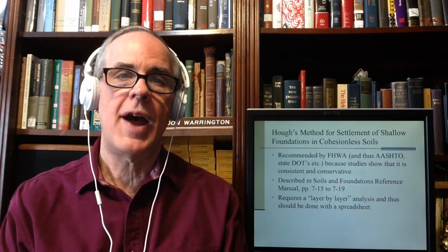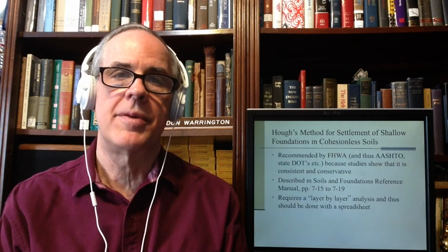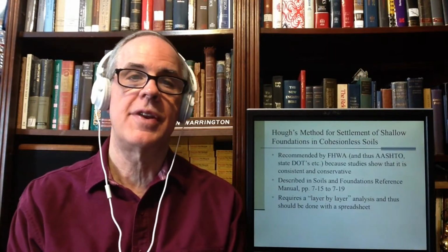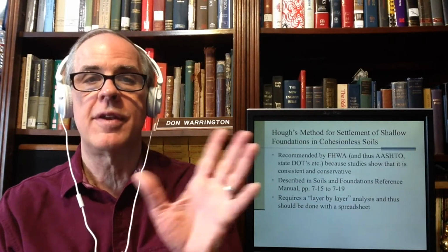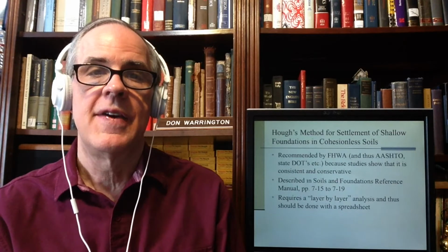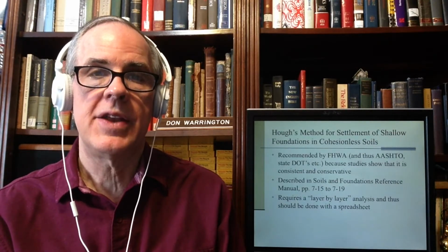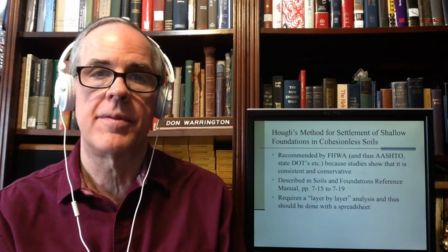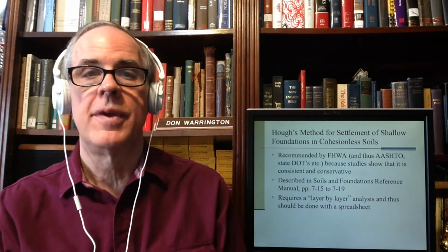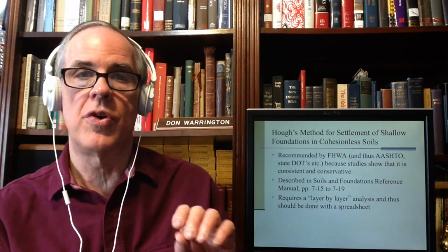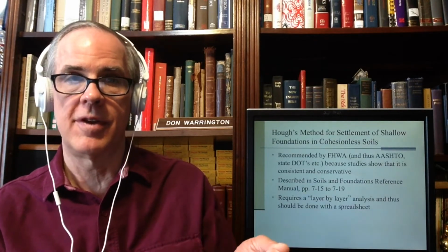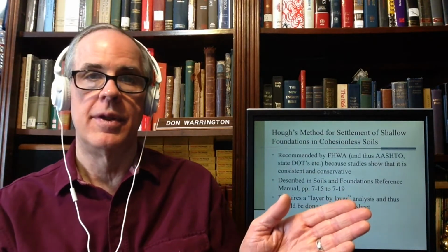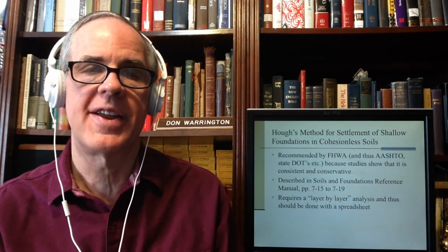And basically, the problem is that in consolidation settlement, we can use the modulus of elasticity to do it. The problem is that the modulus of elasticity, if you rearrange some things and look at the way the test is run, actually increases as we apply further pressure. The problem is not that we can't use the modulus of elasticity itself as a moving target. And we can also show, and I do it elsewhere, that the modulus of elasticity of a soil, or the shear modulus of a soil, and by extension the modulus of elasticity, is related to its void ratio or porosity. In other words, as void ratio or porosity drops, the modulus of elasticity increases, which means that the whole thing kind of hangs together.